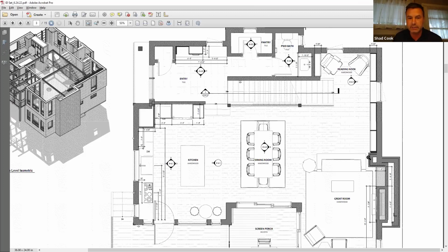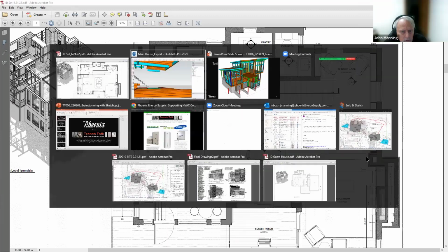Going back to the DX routing with some possible ceiling cassettes, I was thinking one-way cassettes. I've done those in some higher end homes with better success because they are a little more inconspicuous and stay a little tighter to the ceiling, and it's just not where the eye goes all the time, as opposed to breaking up a wall per se. But I would imagine the ceiling level of that second floor assembly is even harder to traverse to, or to mount a one-way cassette in those areas.